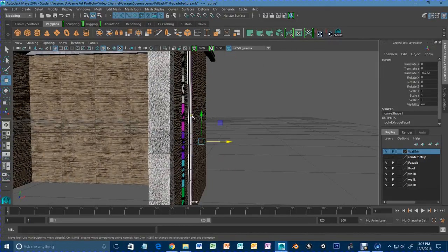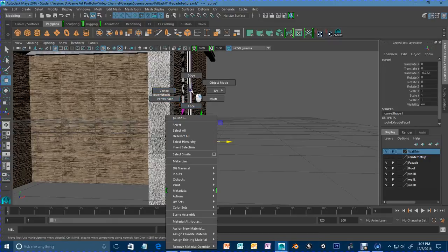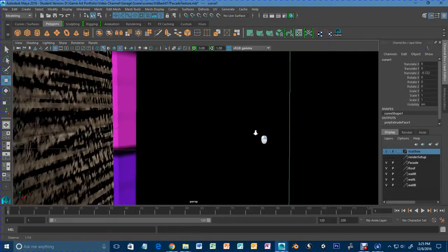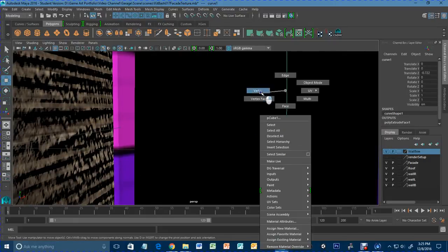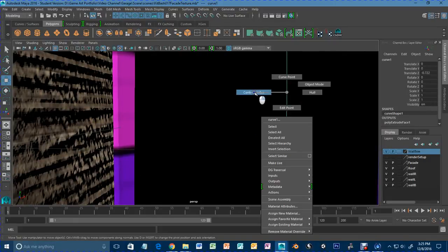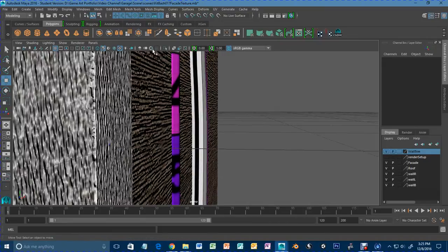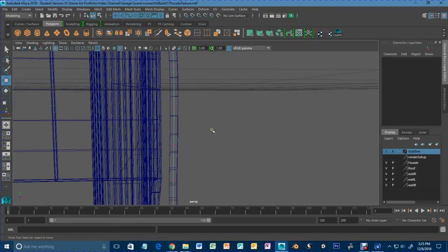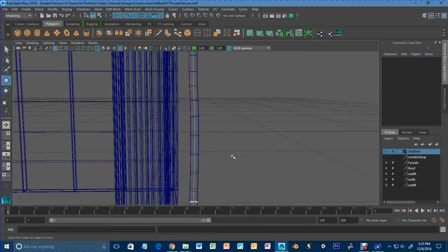And then I could actually, it's a little harder to do once you've actually got the shape. But if I go to my control vertex, well actually, if I just turn wireframe on, it'd be easier. Then I can go in and control the vertex, and mess with that geometry.